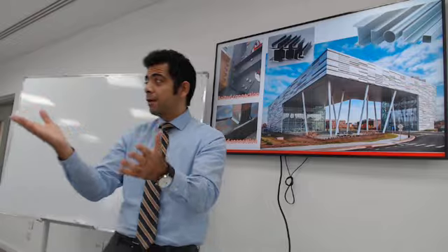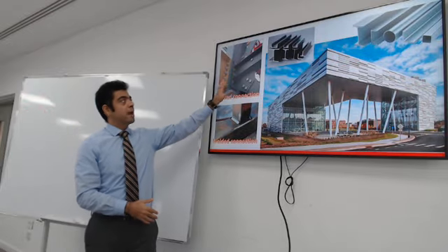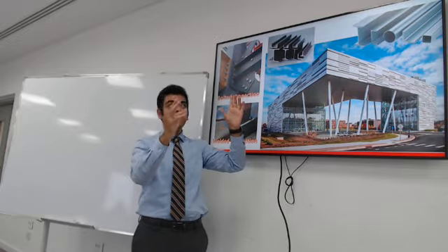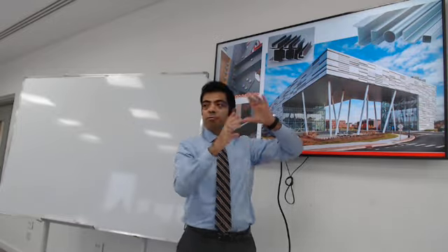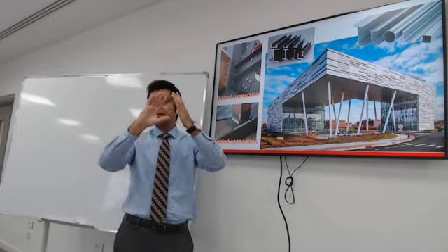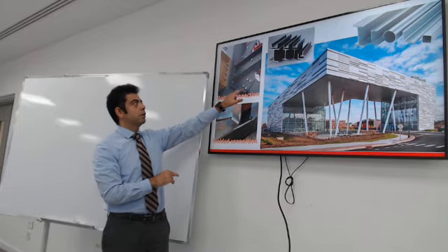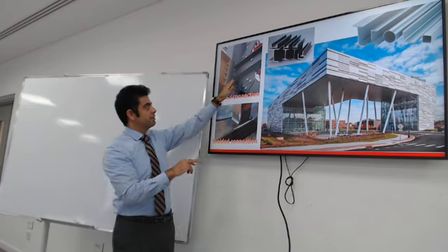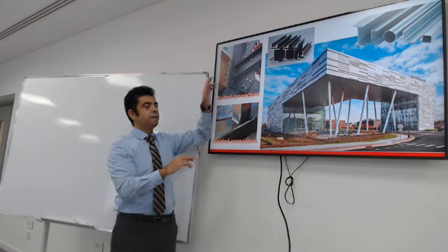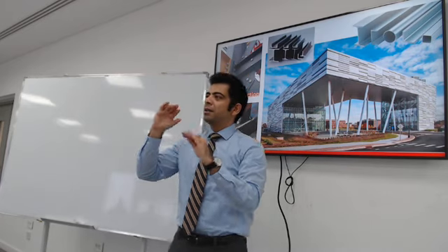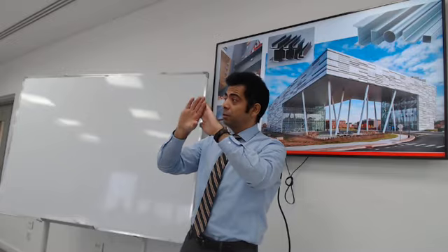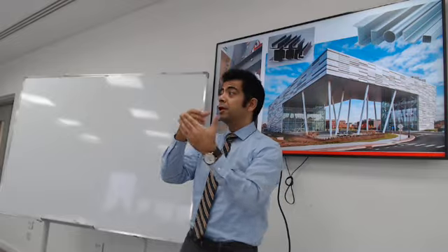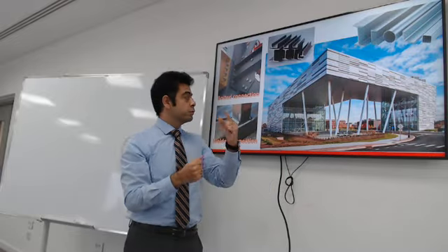Yes, that would be a very valid way to connect these steel elements together. So you've designed a column from an I, you've designed a beam from a C channel, and you want to connect them together. You can connect them using bolts. So you add these additional plates to facilitate or accommodate the connection, and align holes, use certain diameter bolts, and connect them together. You can also weld them.